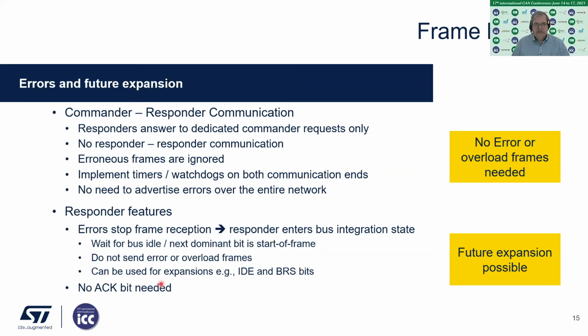And this can also be used for some expansions if somebody wants to implement them, for example, using the IDE bit, or using the bitrate switch bit in case of need. So that means it is also open for other kinds of implementations. And the responders do not need the acknowledge bit. They simply ignore it, or they say, okay, once I have received the correct CRC, I have received the frame correctly, and I'm done.